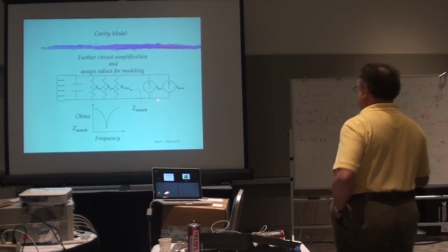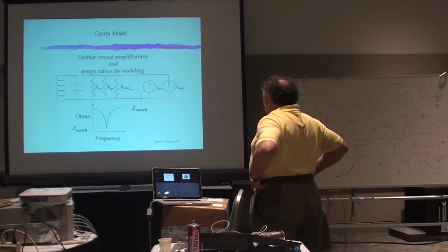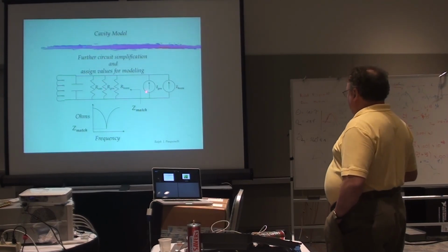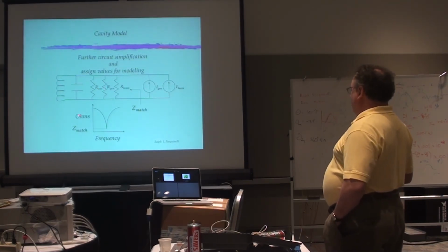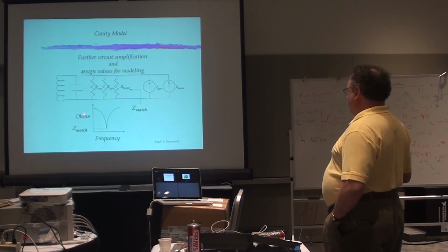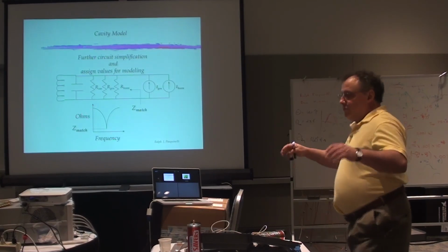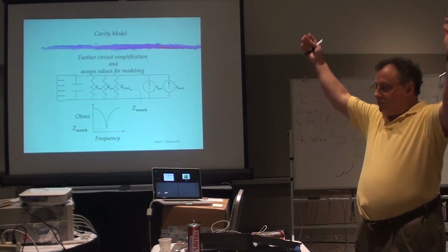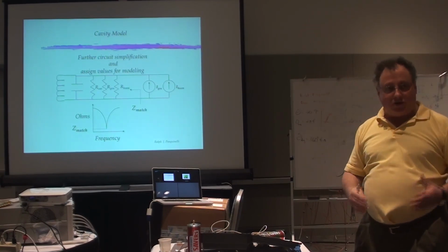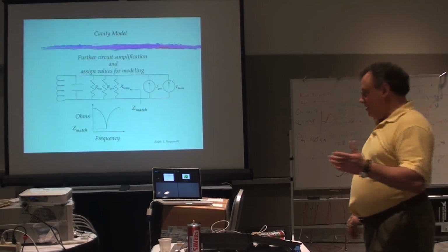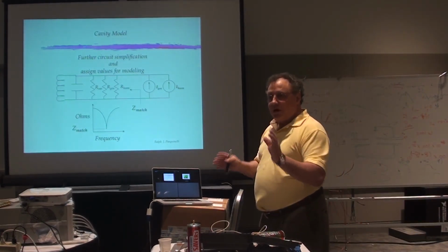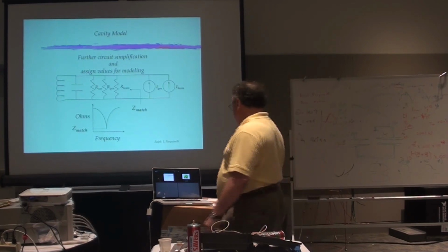And we look at the power generator also as a joint. Well, this is the thing that you end up having to match. If we're just simply putting it like this, you've got an impedance versus frequency. And this is what you guys have been doing when you've been trying to match, those of you who've gotten that far: you're trying to minimize the amount of return loss coming to your source at that frequency. And for a cavity, typically, it is a single frequency, so you can match it really well even with just a single stub, which is nice.